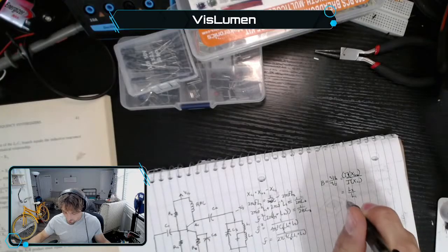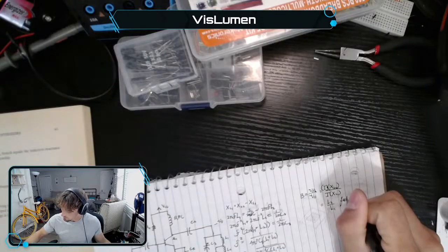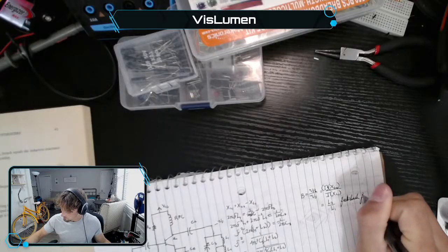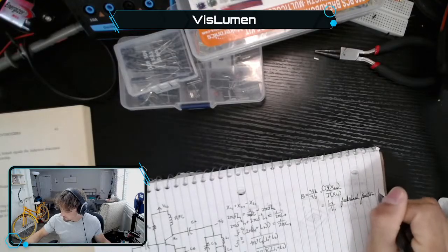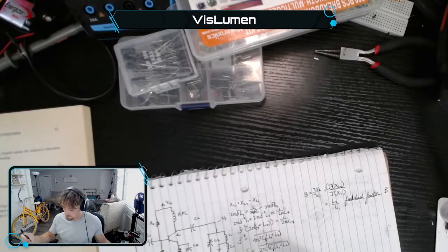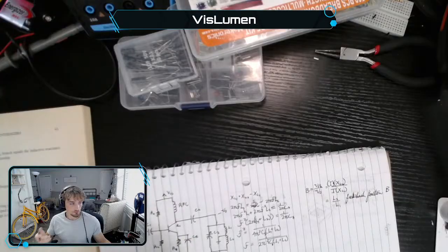As you recall, the ratio of feedback voltage to output voltage is the feedback fraction, B. So, feedback fraction B. Sure. Okay. To satisfy the Barkhausen criterion for oscillation, the AVB product must equal 1. Solving for AV gives us, okay, AV, where AV is the voltage amplification, the gain. It's the voltage gain.